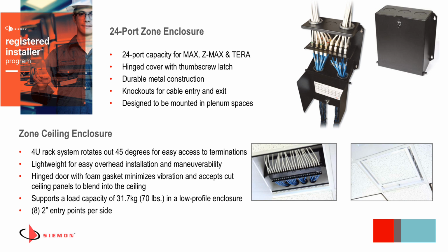So if you consider having a 48-port, 1U patch panel, you can get up to 96 ports in that footprint. But it's a little bit more of a complex design. It has to be attached and suspended from the ceiling above, so it's a little bit more complex to install. And also the connections are all accessible from below the ceiling, which is kind of nice. So you can drop that ceiling panel door open and get to any of the connections, visibly to be able to see what you're doing there.